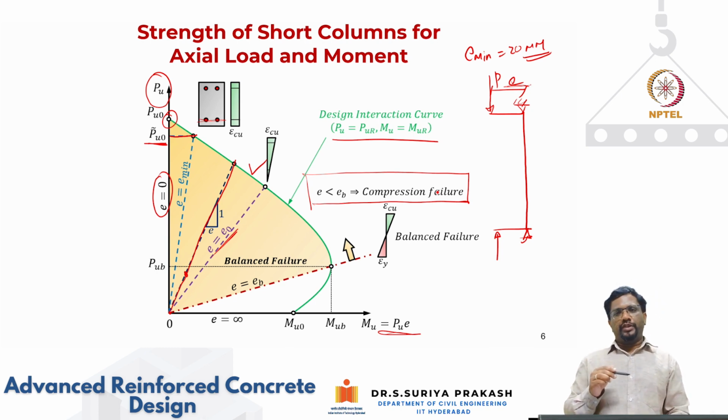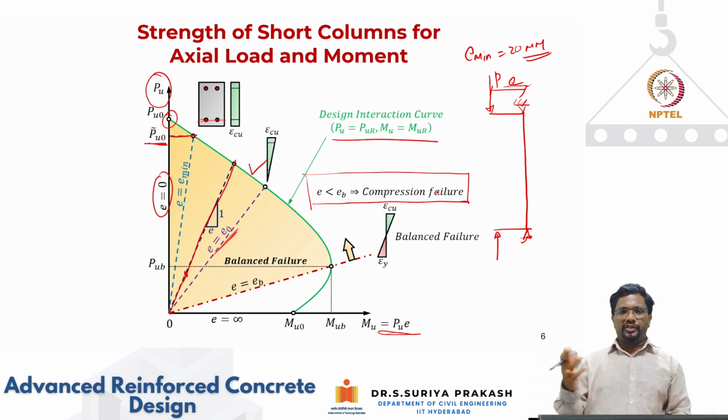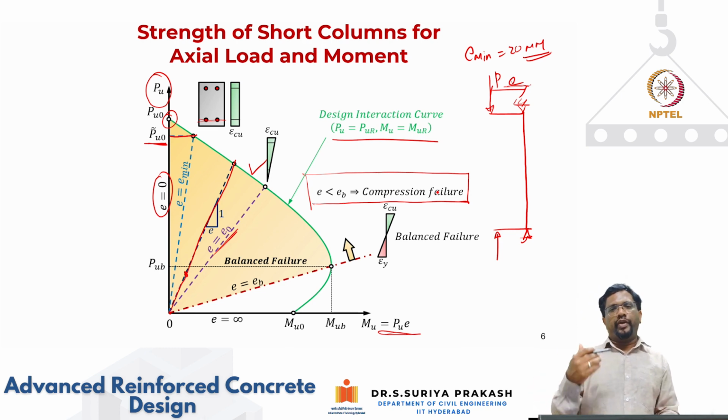In bending, we have seen that concrete is not allowed to reach its failure strength before the steel is yielding. Code wants the design engineers to design only under reinforced sections, right? But here we are dealing with a compression member. So the predominant role of a column is to resist the compression loads. In addition to that, you will have shear and bending also. So we cannot make the column fail always in under reinforced mode. So the code is allowing the members to fail in compression mode.